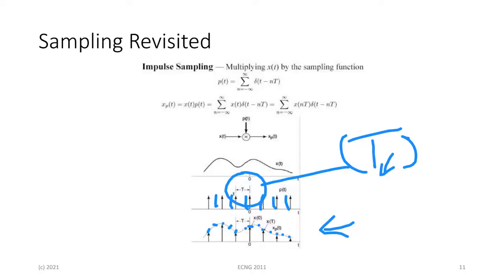Yes, question. Yes, there's one general question, right? So when you switch it on and you sample that waveform and it's stored in the capacitor, and you take it back out, so that capacitor is storing that sampled part of the wave. Does that capacitor have any effect at all on the waveform that we would have to account for afterwards? All of that has to do with another series of things that we'll talk about, not here, but we may get it in electronics, and you will also get it in microprocessors as well. It has to do with the whole analog to digital conversion process. Yes, the capacitor has an effect.